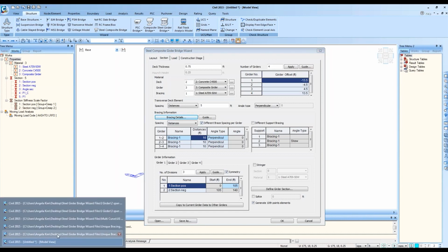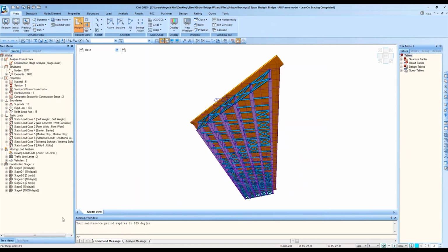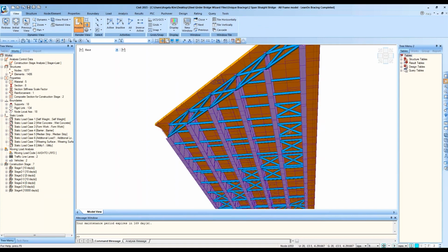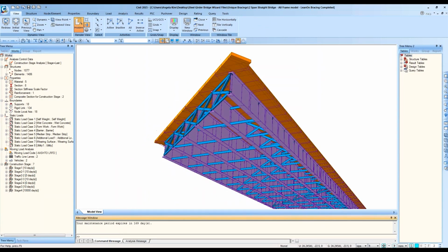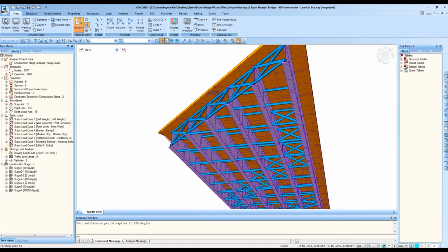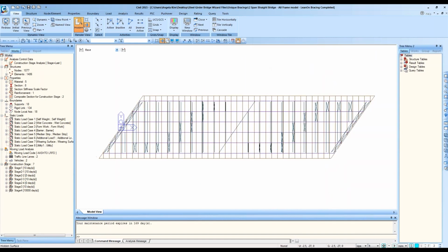Let me show you a couple of examples. So I was able to model the lean-on bracing type like this. I defined 2 types of bracing, one without the brace portions, and then I also defined a full X-brace. And I located them, spaced at different gaps.